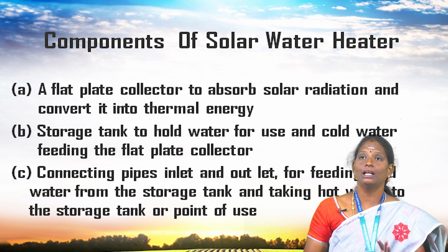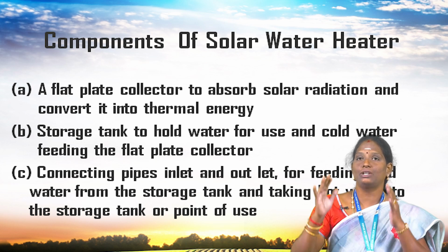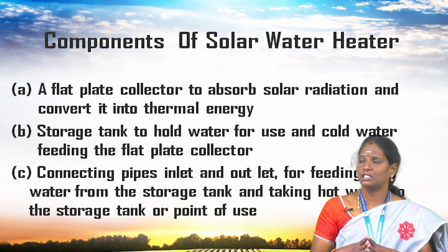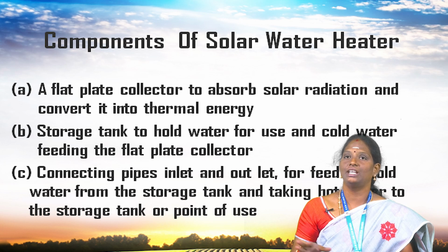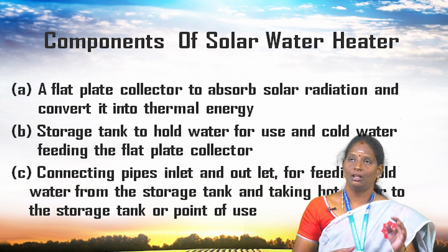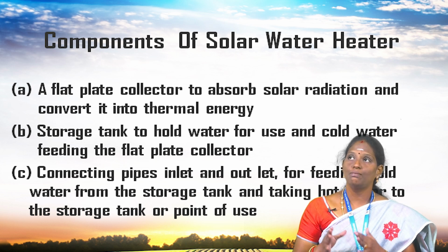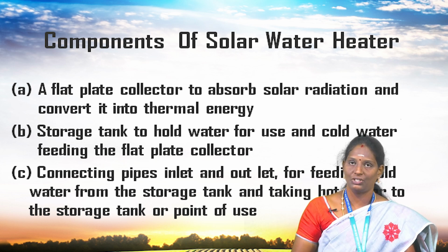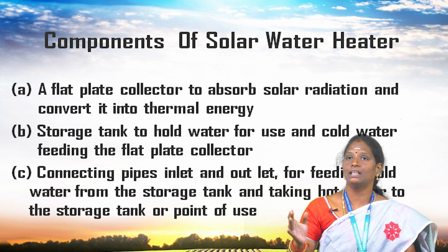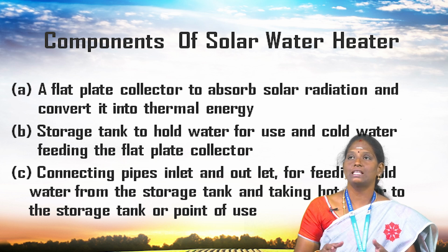Solar water heating is a good example to illustrate one of the assets of the direct use of solar energy. This is the possibility of matching the temperature achieved in the heating device with the temperature required for end use. As a result of this matching, the thermodynamic efficiency based on the considerations of availability of energy can be shown to be higher in the case of solar water heating system than a water heating system using natural gas or electricity.